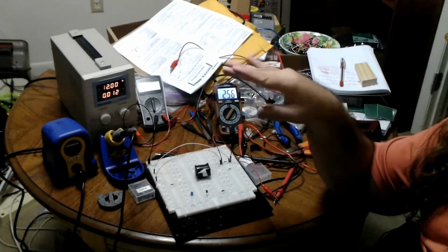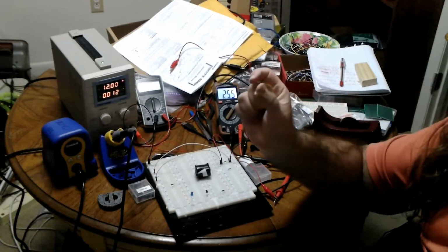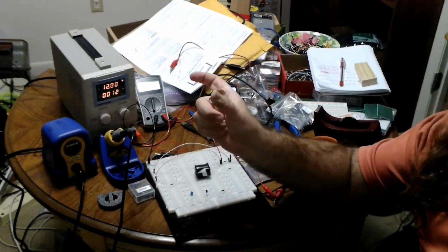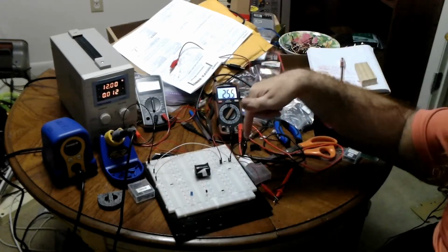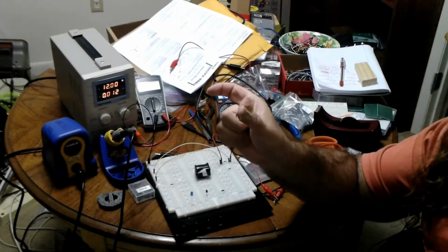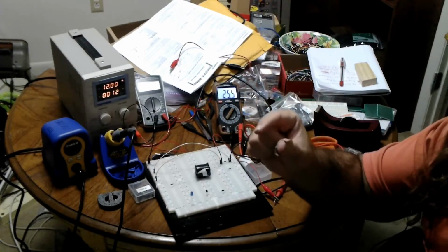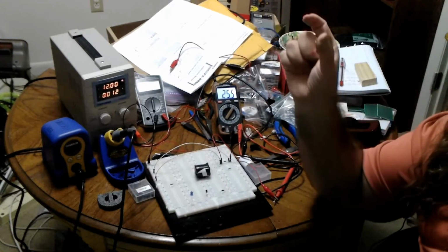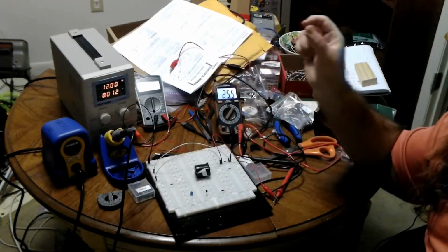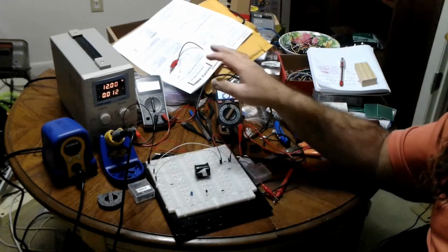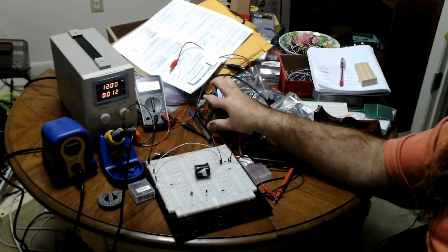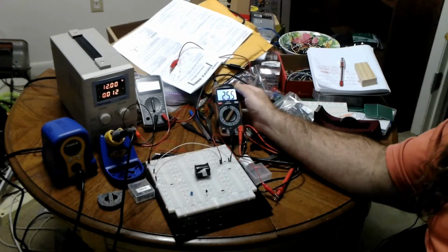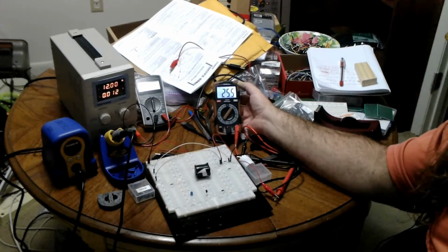So what if this thing is using a diode? When the power is going on the positive side, the diode is forward biased, and it reads voltage minus the voltage drop of the diode. Because it's got a diode, and then it would have a super high impedance resistor. That's how the voltage setting would work, and it's measuring across the resistor. But the diode is going to drop its forward voltage drop. But they know what diode they put in here. They already know what its forward voltage drop is, don't they? So what if they take whatever reading they get, and then they add the known forward voltage drop and treat that as the actual reading when the diode is forward biased? Now, without opening this thing up or looking at schematics or something from the US Patent Office, I'm not going to know that's how it's done. But it's pretty doggone likely, isn't it?